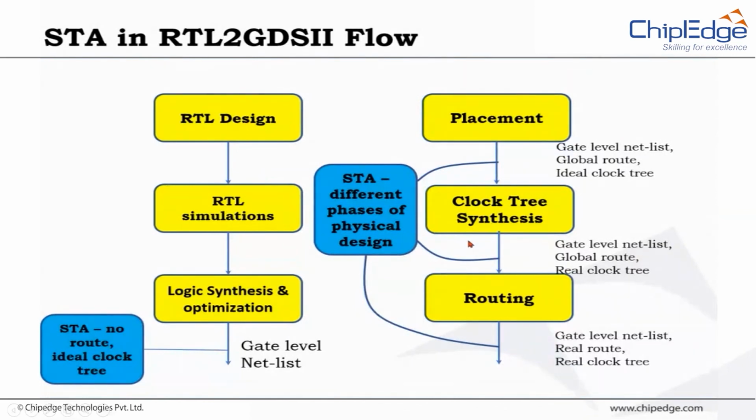So obviously the signal flowing through such load will transition very slowly unless you do something special to address its load requirements. So that is where we build what is known as a tree, where you have a buffer tree typically, where you have one buffer feeding something like 6 buffers, let us say, each of these 6 buffers feeding another 6 buffers, and so on and so forth. Like we build a tree of different levels, and that is called clock tree synthesis.